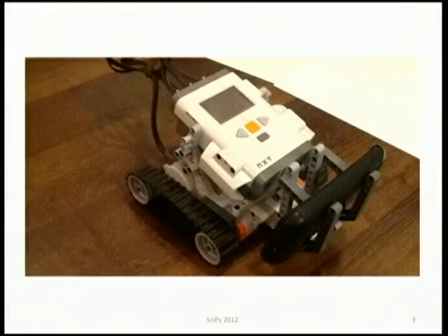I used the Lego Mindstorms system for the physical build of the robot, and that helps to simplify part of the process. So this is the robot, the way it looks, pretty small. It's a two-tracked robot, so there's independent motors for the left and right track. So the differential drive, I guess, is the term. The interesting thing is there's an Android camera phone mounted in front of the robot. And that lets the robot see what's in front of it, and it can move around.